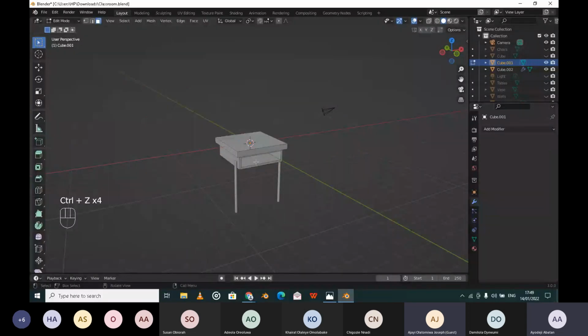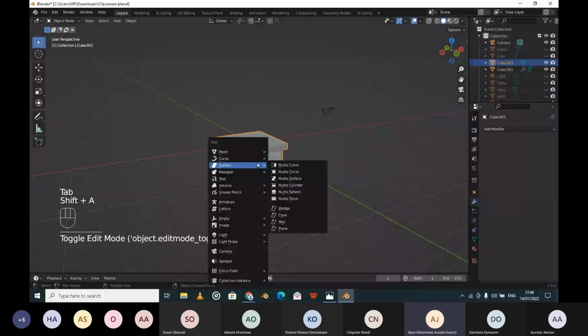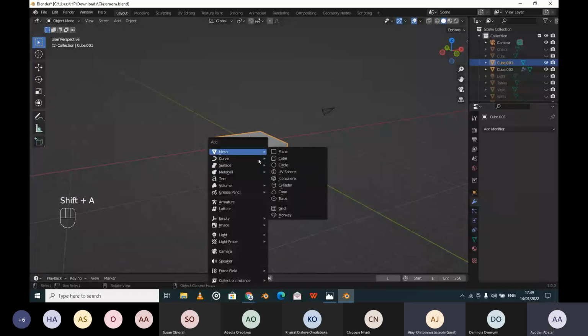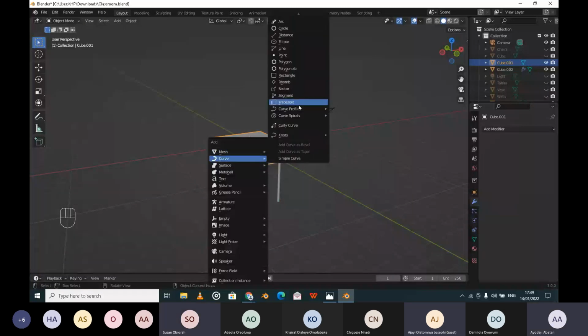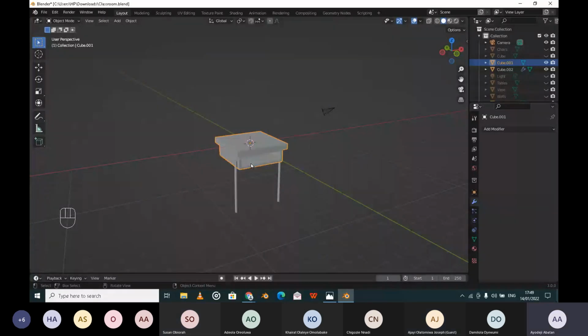You should have come out of edit mode to add your legs. The legs for the table, the cylinders. You created the cylinders while you were in edit mode for the cube. Am I right? Yes. You should have stepped out of edit mode to do that, because creating it while you were in edit mode for the cube parented the cylinders to the cube. So anything you try to affect on the cylinder will also affect the cube.